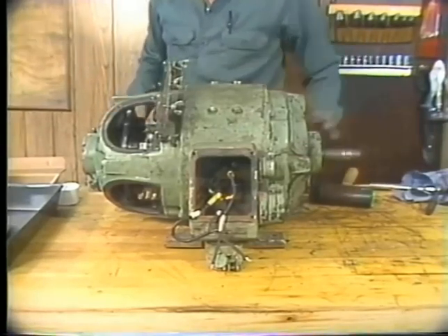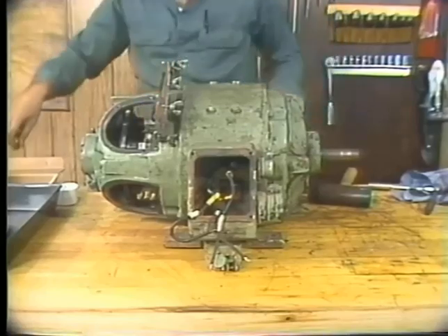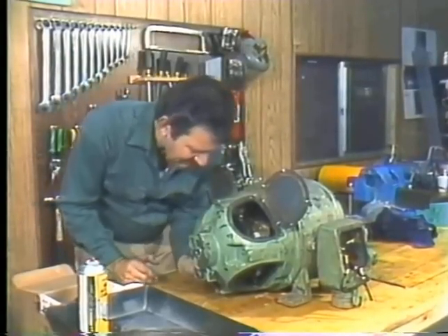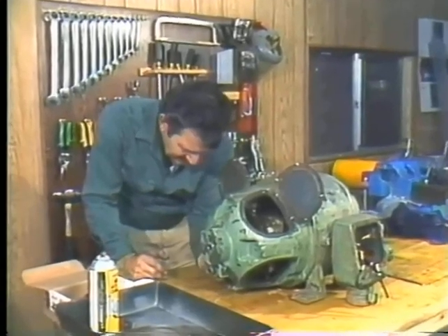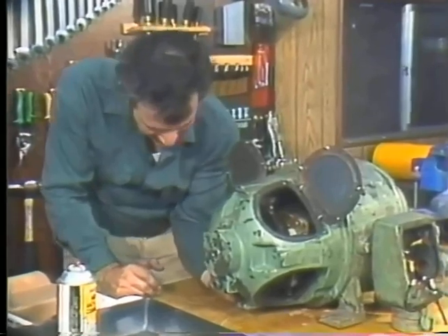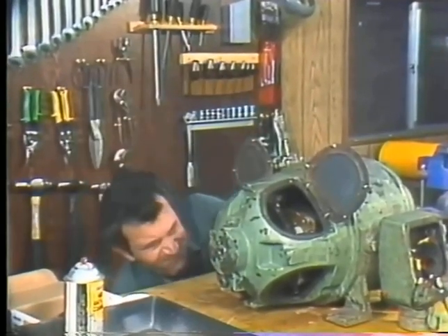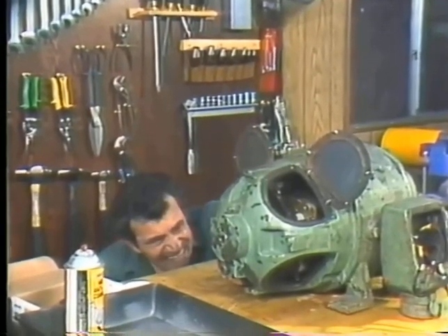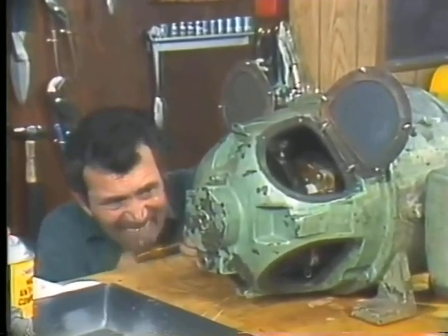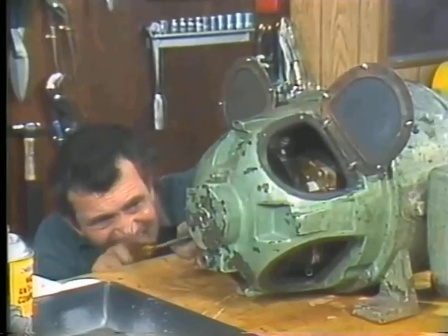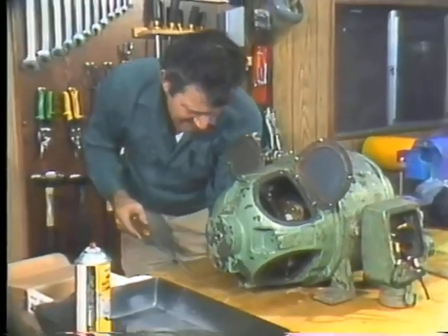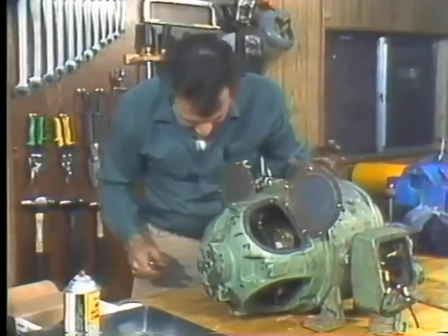Be sure the end bells are on straight and the end bell bolts are tight. Now, if this all looks good, you may have a bad bearing. If this is the reason for the motor not turning freely, it will have to be taken apart again and the bad bearing replaced. Never start any electric motor unless the shaft is free to spin when turned by hand. Now, connect the field coil leads to the brush rigging. Make sure the connections are clean and tight.